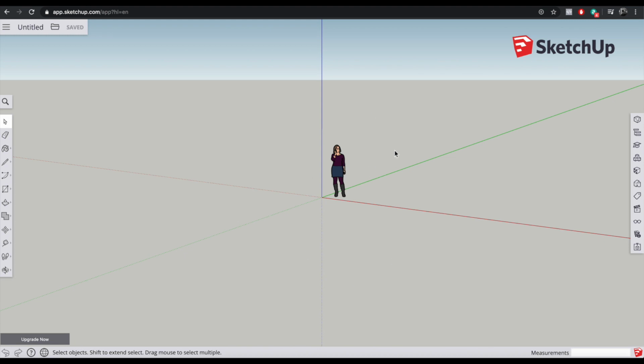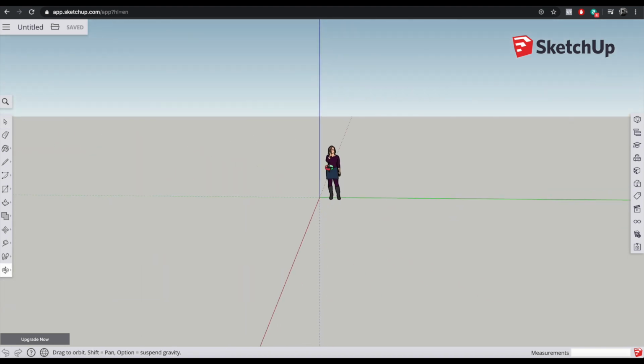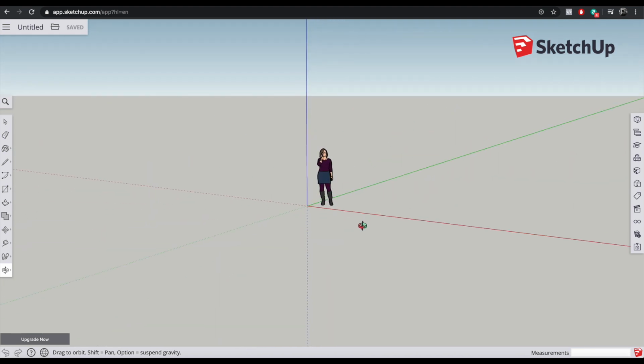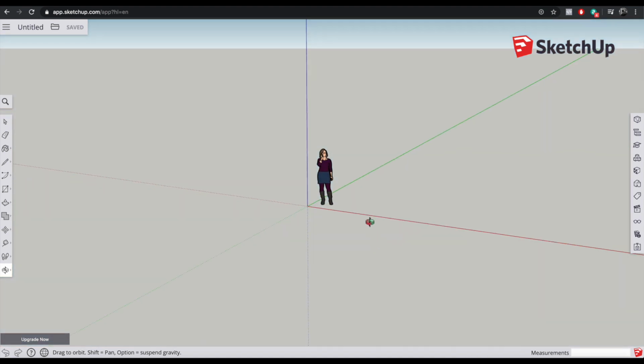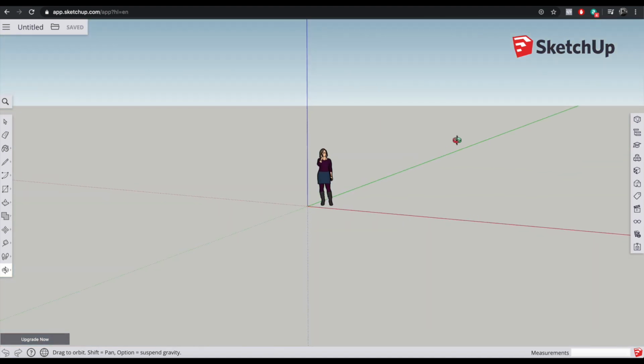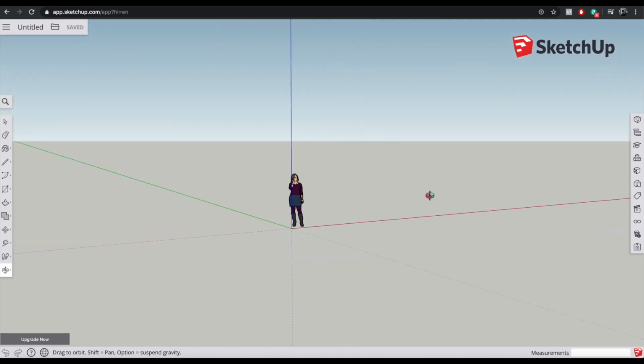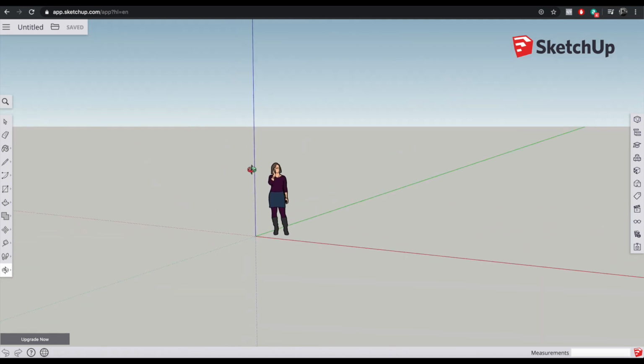In the center, move towards the figure in the center of the screen that gives it a bit of a sense of scale. Next, if you look on your toolbar on the left hand side, this tool at the bottom, you will use an awful lot. It is the Orbit tool. If you just click on that, you can then click and drag and you can move around the scene. You can go below the workspace or above it. And you will want to get used to zooming in and out and navigating around. So just get used to using this three-dimensional space.